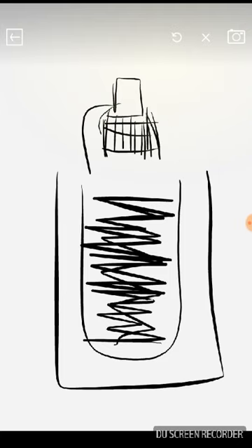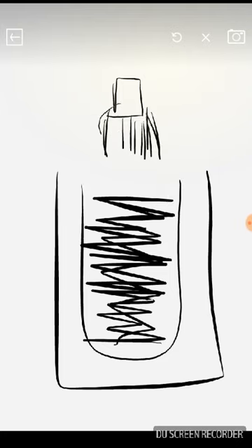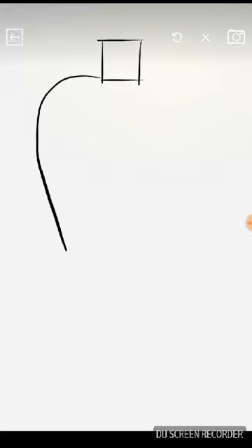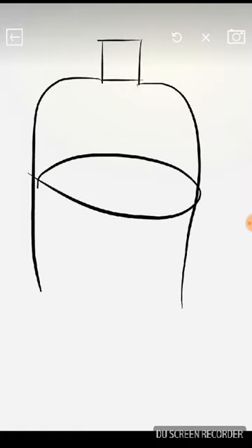To determine how thick in radius we want this circular wafer to be, we rotate the seed crystal such that the extra particles can drop off. After that the seed crystal is slowly pulled up, and what we get on the seed crystal is a totally circular bar of silicon from the furnace.